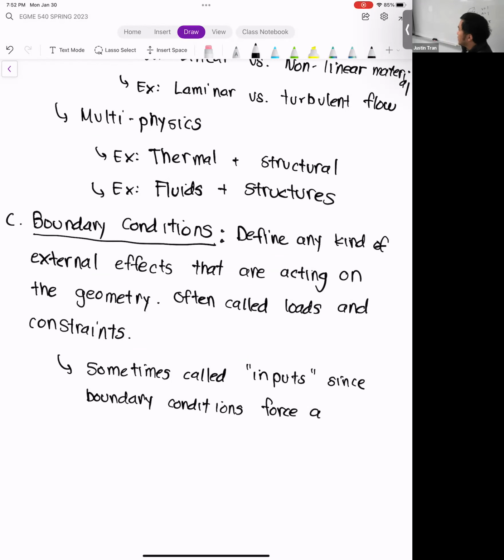because there are a lot of external effects where maybe it's really difficult to encapsulate it as just a single force or a single load. For instance, maybe you'll see in activity 3 that we're going to analyze a freeway sign, and one of the forces that we're going to exert on it is a wind force. One way that you can model a wind load is to apply a uniform pressure throughout the entire sign. But that may not be exactly accurate. Maybe the wind's blowing faster on one side of the sign than the other. But you have to specify the boundary condition in some way. And so you make an assumption in terms of how you apply that force.